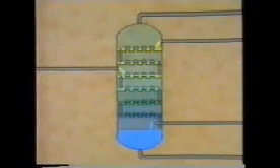A mixture that is hard to separate, one whose components have boiling points that are close together, usually requires a high reflux ratio. A mixture whose components have boiling points that are further apart is easier to separate. This kind of mixture will normally require a lower reflux ratio.